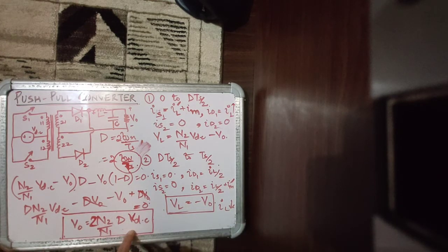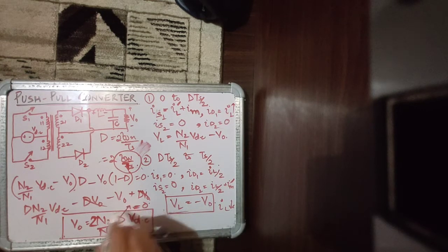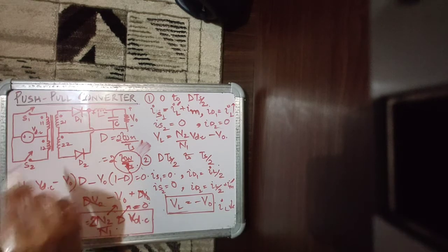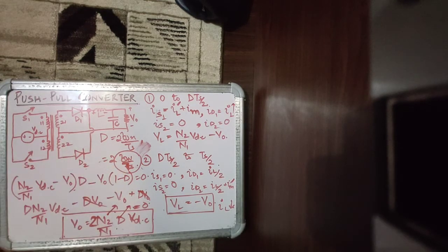Again, it's a Buck derived converter, and you also have turns ratio appearing in the output voltage relationship, so you can have fine control as well as coarse control. Fine control through D and coarse control through the turns ratio of the transformer to control the output voltage. And the benefit that you're getting is that your core will get excited in two directions.